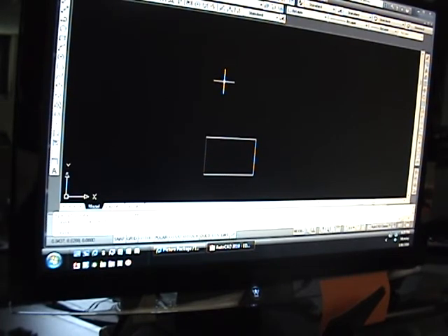We're going to project some lines up here. It's going to be 2 inches. It'll have the same width as the front view, with the exception that this one is going to be 1 inch tall. 2 inches, and then it's going to close.